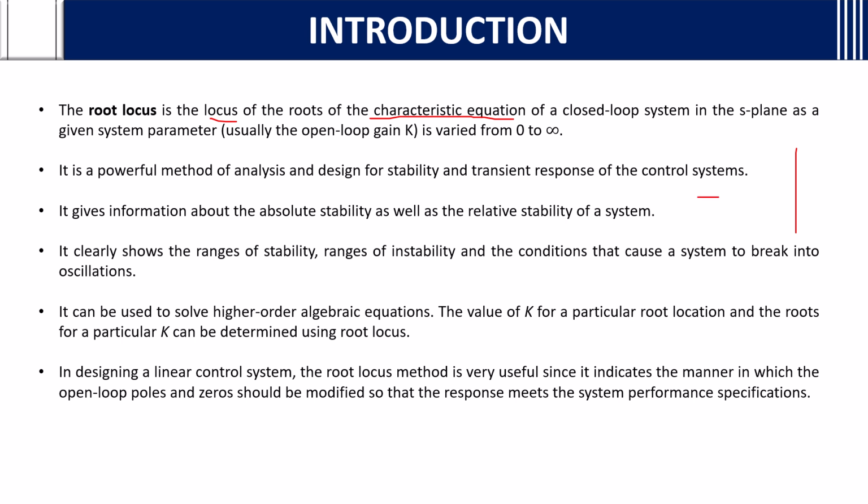You know there is an S-plane with an imaginary axis. In the S-plane, you will plot the poles and zeros of a closed loop system for a characteristic equation. These loci of roots in the S-plane, as the open loop gain K is varied from 0 to infinity, is called root locus.